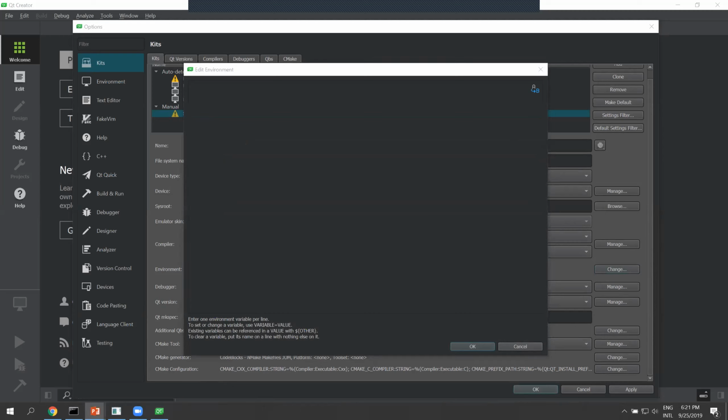And then I will just copy paste these, but I'm going to explain to you what it does. Of course, you will need to adapt the paths here to the locations on your machine. But the first line is the ARM GCC dir, and you should set here the location where you install the ARM toolchain.